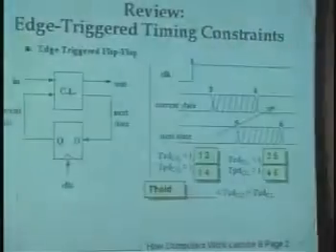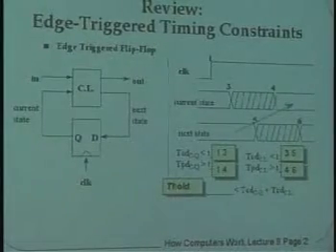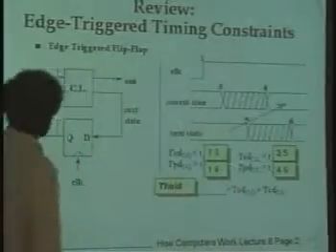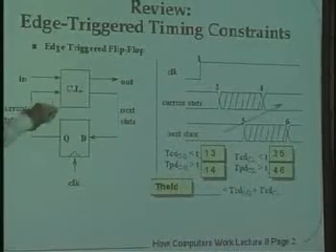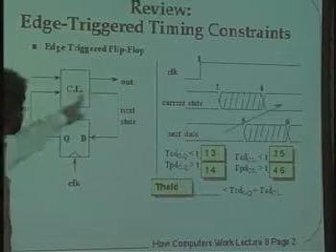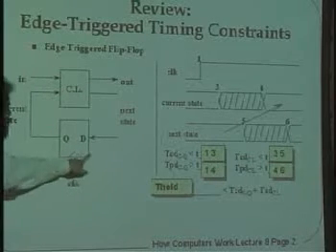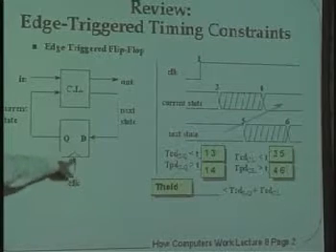But let's begin with a little bit of review, taking a look at some of the timing that you've been learning about at the end of the last week. So if you remember, here we have a typical synchronous finite state machine, and it consists of some combinational logic and input and output and some feedback that, if you remember all of our examples, goes through a synchronizing delay or memory element, which is this flip-flop right here, clocked by the clock.